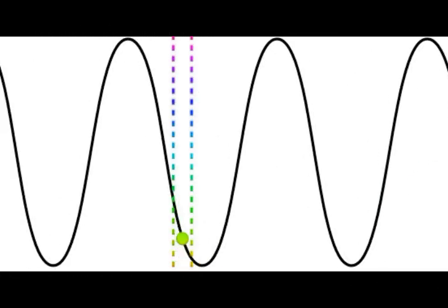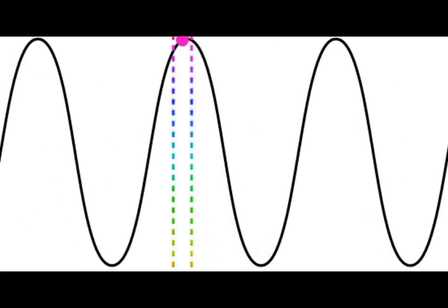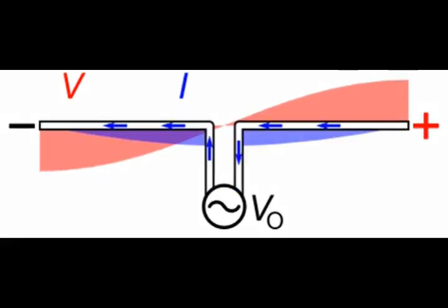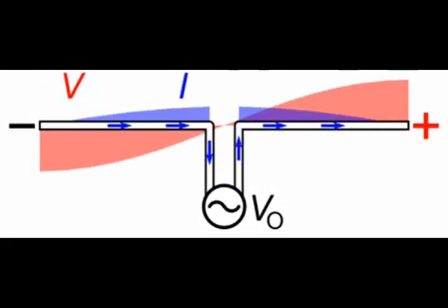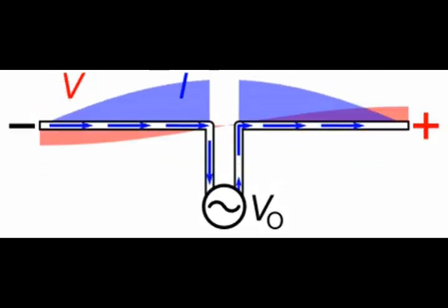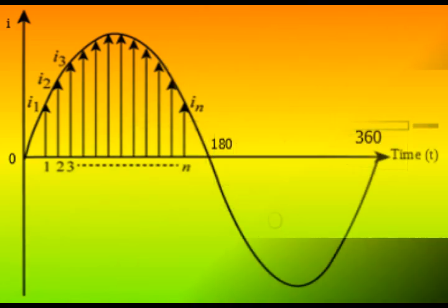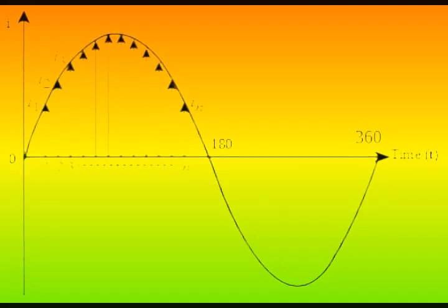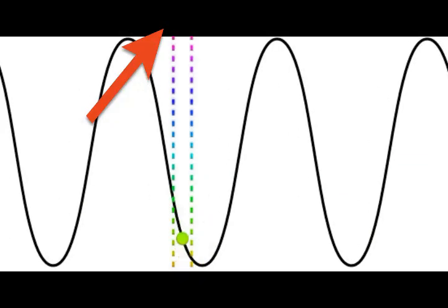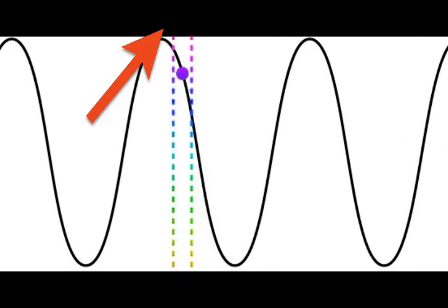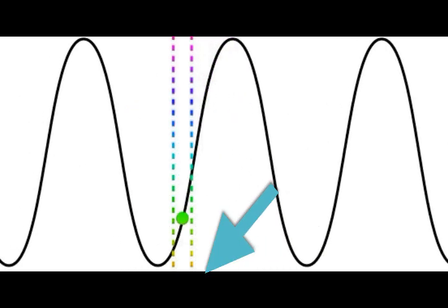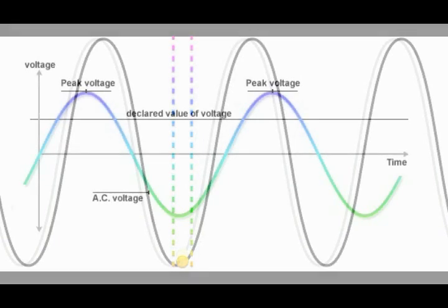The second number specifies the current value or the voltage range on the y-axis. This number is the instantaneous value from 0 to peak or maximum: V max, A max, I max. The waveform shows the largest amplitude before reaching 0 again. For a sinusoidal waveform, there are two peak or maximum values, one for the positive half cycle and one for the negative half cycle.